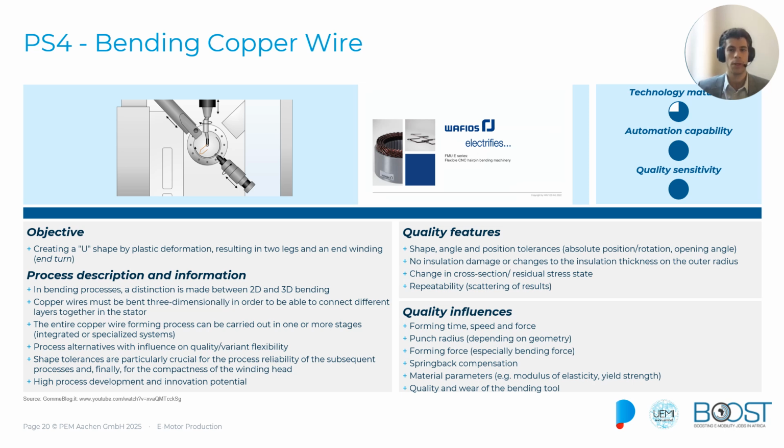The quality is influenced by the forming time, speed, and force, as well as the material parameters. These could change with different aspect ratios of the conductor or different materials of the conductor, like aluminium or copper.